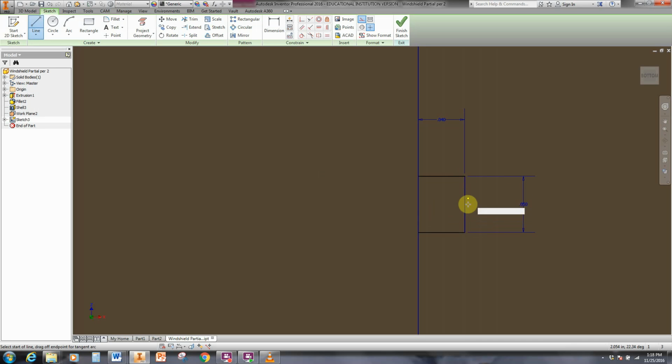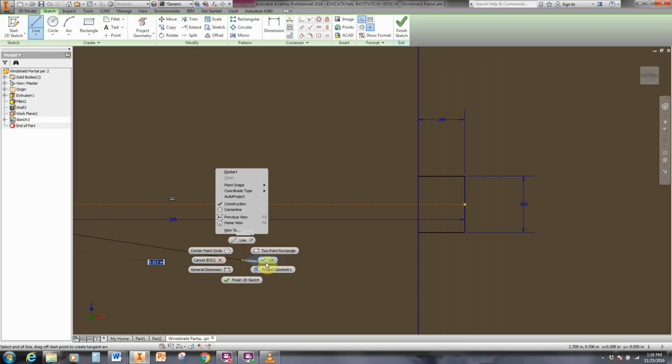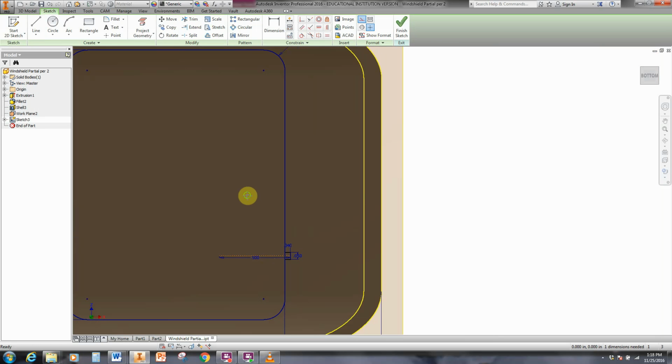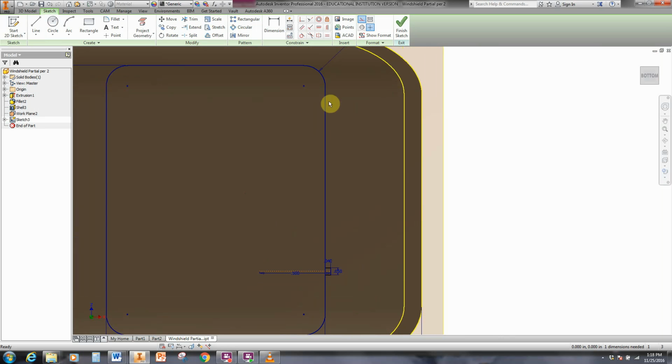You get a green dot in the corners, right? But we want the midpoint. So we get a green dot there. And then I just draw my line at a nice 180-degree angle and 0.5. The dimension, the length of this construction line is not important, only that it's long enough that we can see it. Right click OK. So now we zoom out a little bit so we can see the right side of our rectangle, that red line.